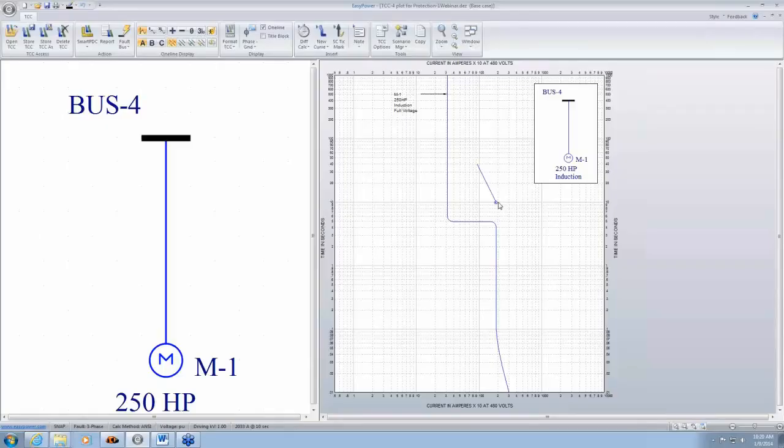When we start the motor, the starting current is very close to 6 times, so that is approximately the locked rotor amps. And the maximum stall times are specified by the motor manufacturer, and this can correspond to the motor class, like you might have class 10, class 20, class 5, etc. And that corresponds to the stall time of the motor.